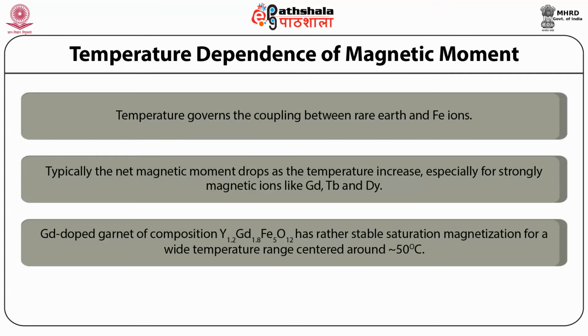So, garnets can be quite useful materials in microwave applications because of their high electrical resistivity and hence lower loss around microwave frequencies. The material is also easy to synthesize in bulk and polycrystalline ceramic form. It is also available as a single crystal or thin film, and moreover the structural parameters as well as the magnetic properties can be tuned by tailoring the composition of the material.